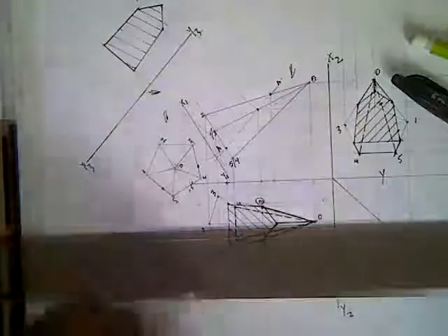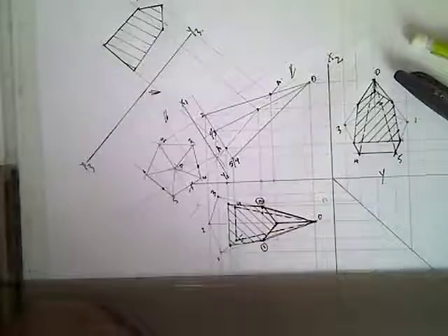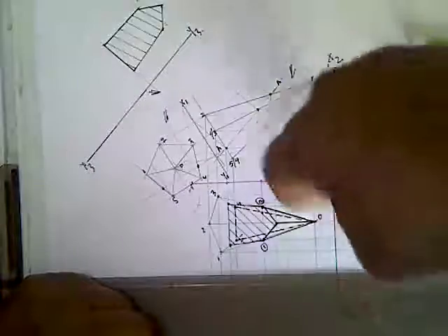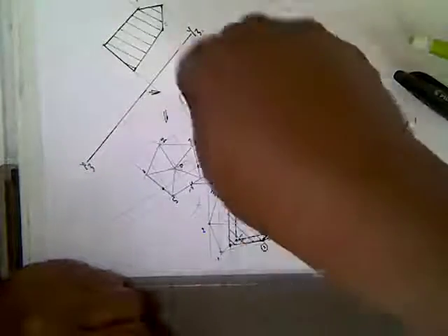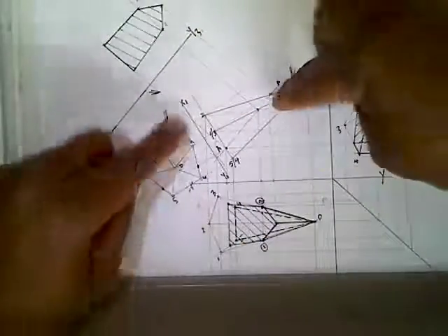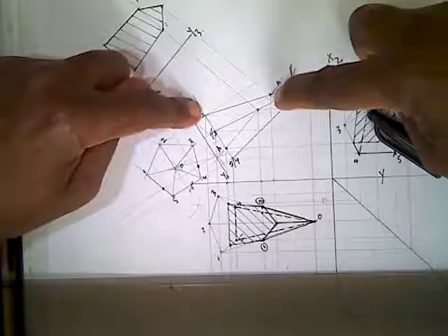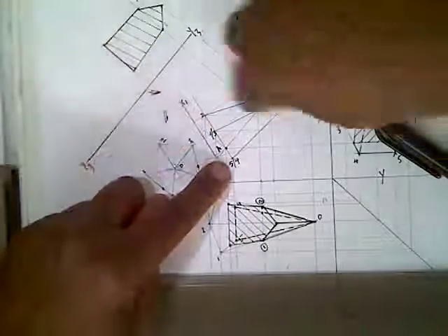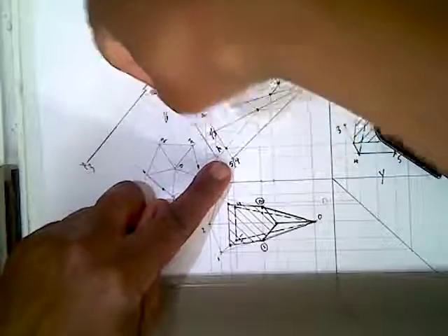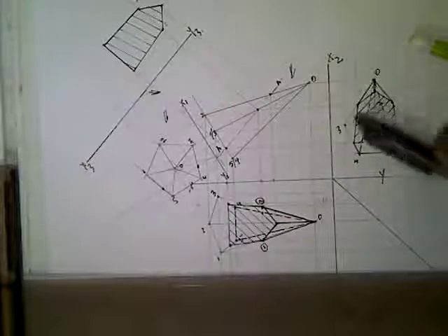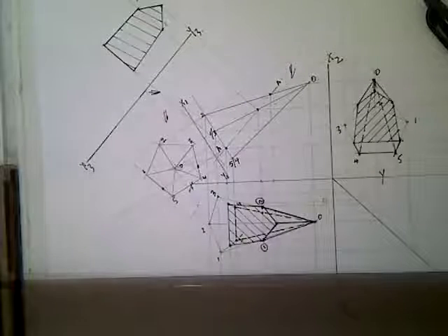These are the true lengths. You must have the true lengths for you to be able to look at it from the true shape. The true shape, you're looking at it at an angle of 90 degrees. When you look at it here, you are looking at it directly from this side. This length looks like it is that length, which does not give us the true length. But once you look at it perpendicular at 90 degrees, you'll be helped by your auxiliary view. You will have it that way.